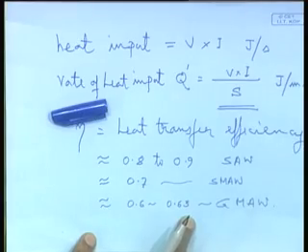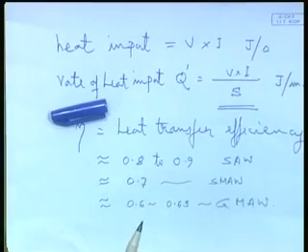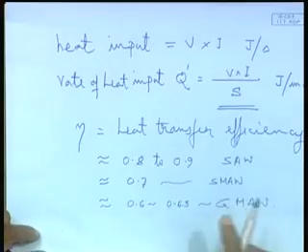So, that is taking a lot of heat. So, it is so less, 0.6 to 0.65, and shielded metal arc welding is somewhere in between, because there also flux is burning and forming the slag, it covers that molten pool. So, heat loss is less. Anyway, so this is the heat transfer efficiency.